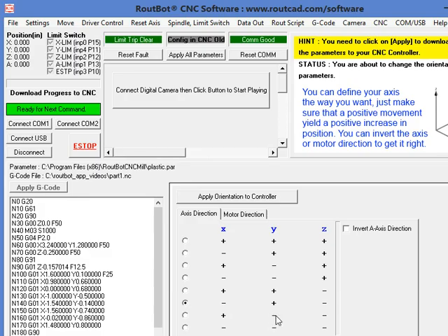But let's say there was a problem with the z-axis. When you're moving in the positive z direction, because we just fixed the motor, the actual position is going negative. You get a decrease in position. You only need to change the z. So you need to go to minus, plus, plus. You look for that combination, minus, plus, plus, which is over here, and that will be your new axis orientation.